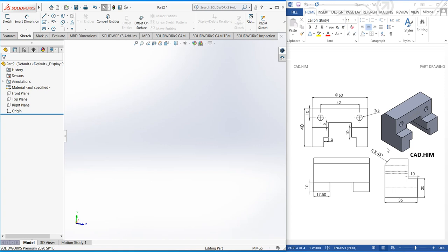Okay. So I'm not going for this first angle and third angle projection. I'm just going for this drawing. So how can we make it? We can either make this loop, this whole loop, and extrude it up to a distance of, I think it is showing us dia 60, but dia 60 is not there. It is the length 60. Okay. So I think there is some misprint. So this dia is not, this dia is 60 there. So we can make this loop and we can extrude it up to like this, up to 60.